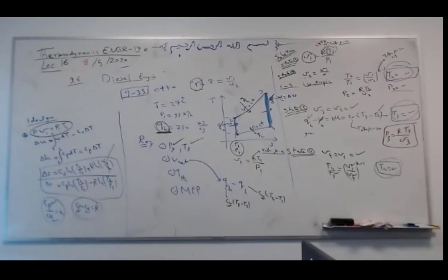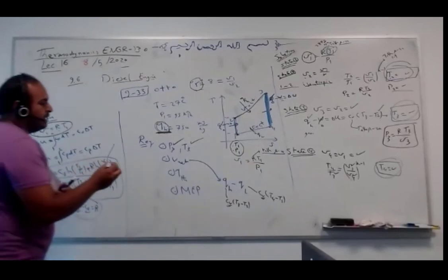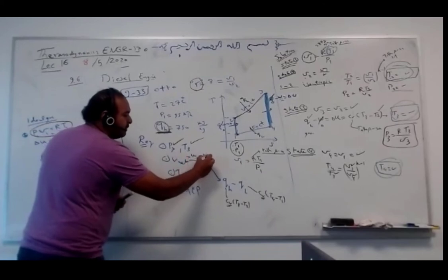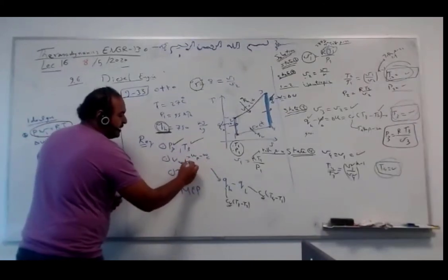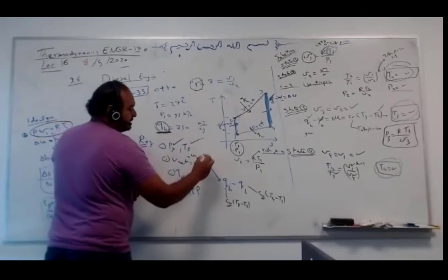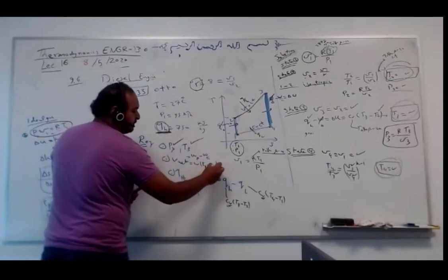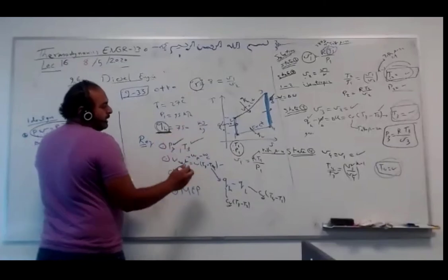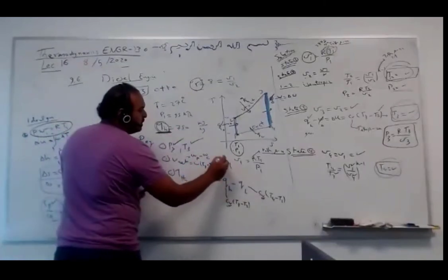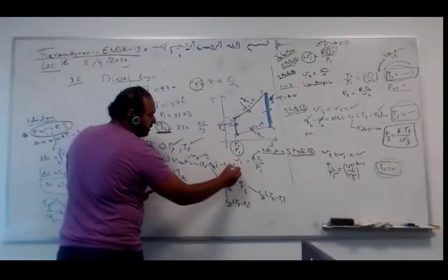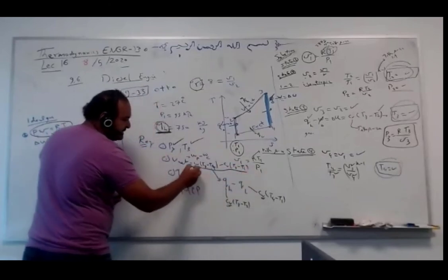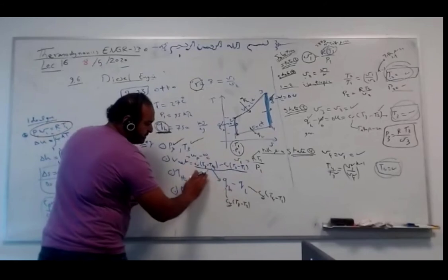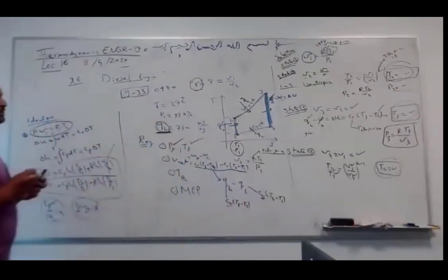If you want to use that, it's okay, it's up to you. So if you use W power minus W compression, the power work is CV times (T3 minus T2), bigger minus smaller, minus T4 minus T1. The compression is CV also, bigger minus smaller, T2 minus T1. If you simplify this, it's exactly the same equation.